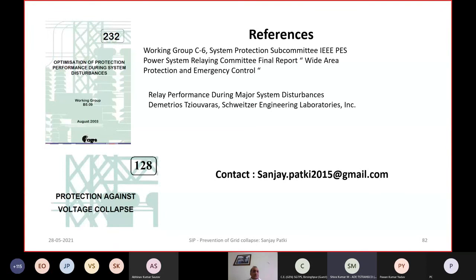If there is a fault inside the winding, sir, then differential will block. This earth fault will also block, no? Then there is no backup protection. No. The relay will be able to distinguish between the inrush phenomena and internal fault phenomena in the modern relay. So that worry is not there.